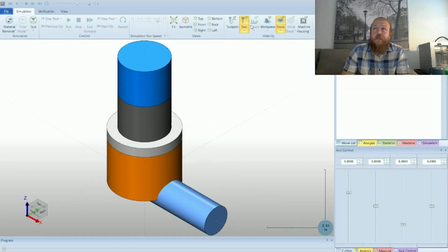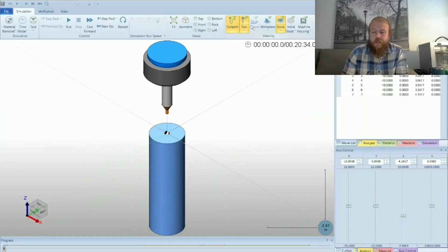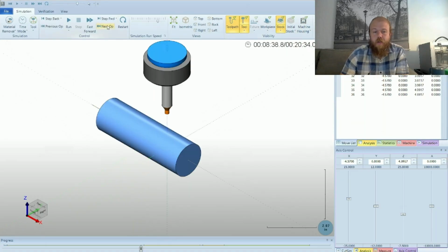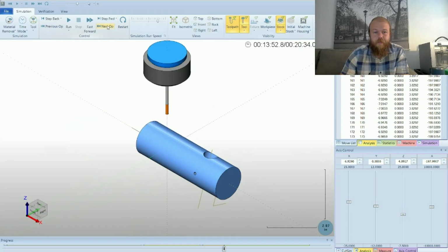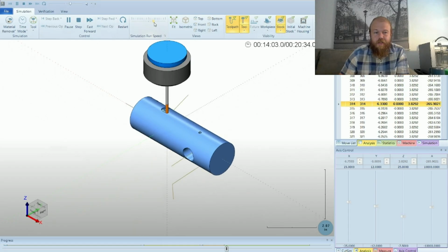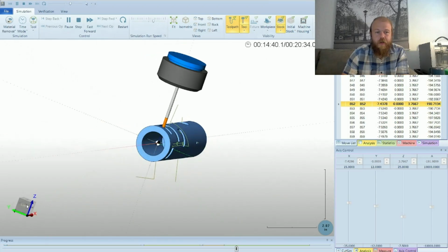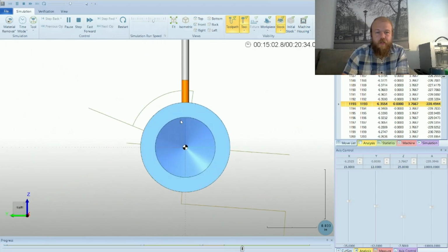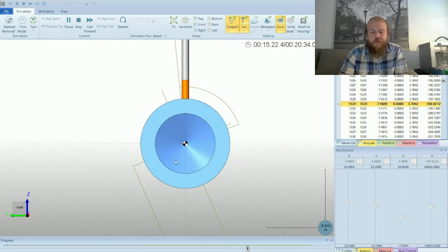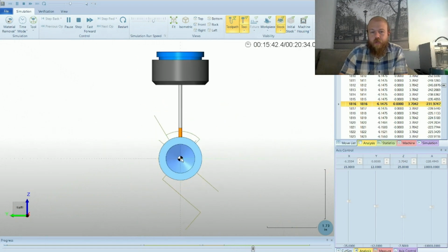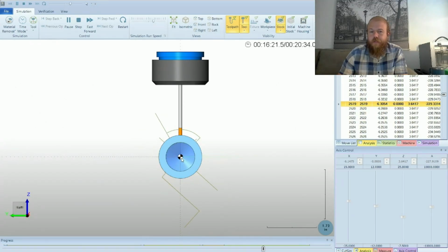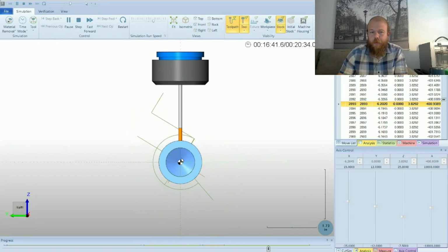So those are all of the different 4-axis standard milling operations: our index, our rotary toolpath, and our wrapping group. Those are all in the 4-axis standard. And then we'll look at the difference between the 4-axis standard and the 4-axis Pro. We can sort of see it right here in the 4-axis standard. The tool is going to stay pointed to the center line of rotation in the 4-axis standard, so sort of like a 3+1 operation.